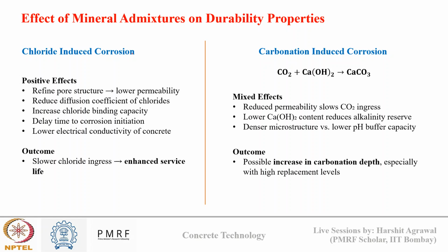Now, this system of reinforced concrete was earlier supposed to be inevitable. We said that reinforced concrete is very compatible in nature. Concrete has brittle properties, steel has tensile property, and they both complement each other and they have infinitely long lifespan. However, in aggressive environmental condition, reinforced concrete can degrade, which can raise issues of durability concerns. And major durability concerns in reinforced concrete come due to corrosion of embedded steel reinforcement.